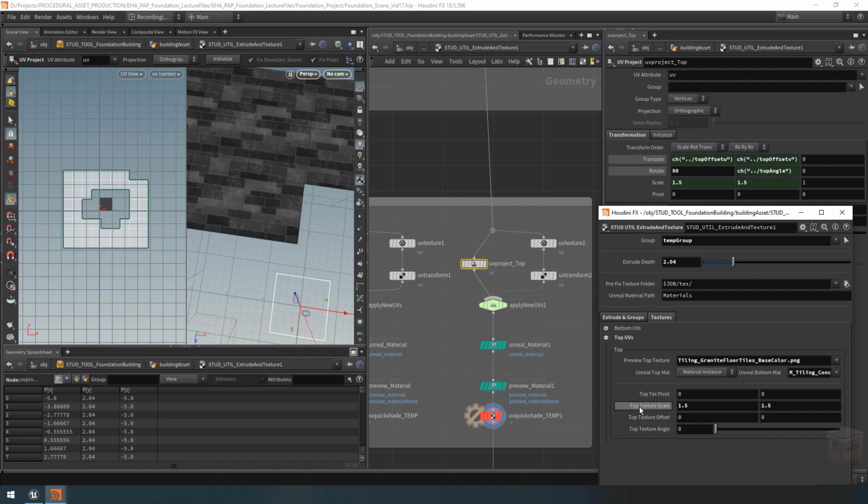So we're not actually moving it in UV space, we're moving it in world space. So to fix that, what we want to do is grab our scale, in this case in X, and multiply our translate X with that. So let's do this. Set it up like that. And then I'll copy the second scale value and multiply that by that.